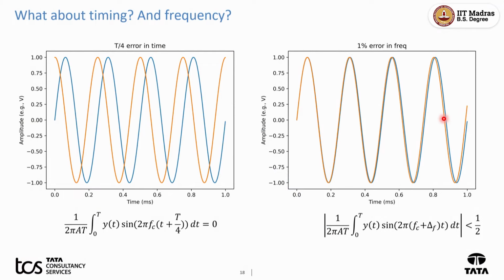It is not possible otherwise, because whatever you do, if there is even a slight difference, the phase will accumulate, and at some point it will look like the left graph. The phase will keep on accumulating. See, already this orange has moved a little to the left, correct? Here it is a 1%, 1 in 100; 0.1 per million can't be visualized. But if you let this happen again and again, at some point this correlation itself will be a cos wave, with a frequency equal to the difference in the two frequencies.